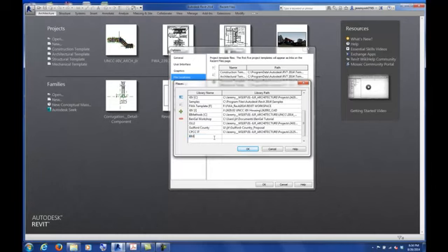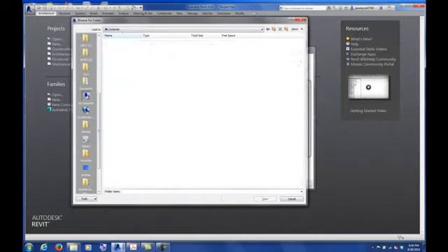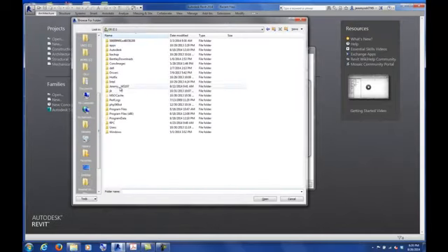I'm going to call this BIM Methods, because that's this fall's class. If you click to the right, you can click into that white space. This is something you'll see often in Revit. When you click into the white space, a little button appears off to the right. I can click on it, and now I'm going to browse to the location on my computer where I'll be saving all these files that I constantly work on, specific to this class.